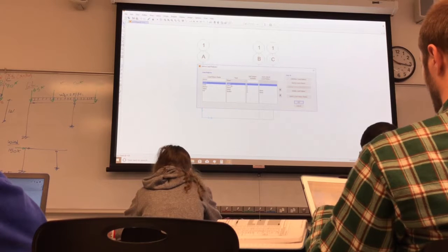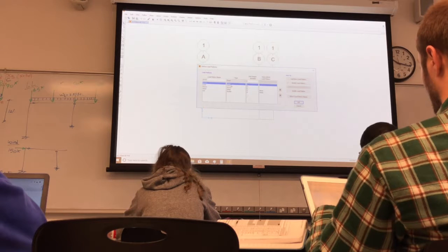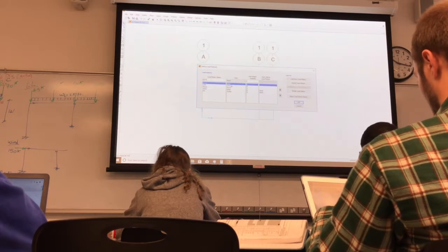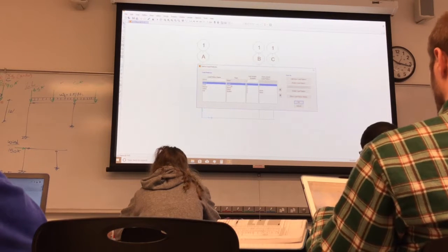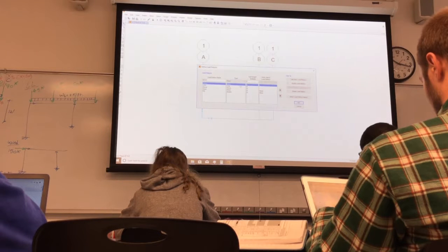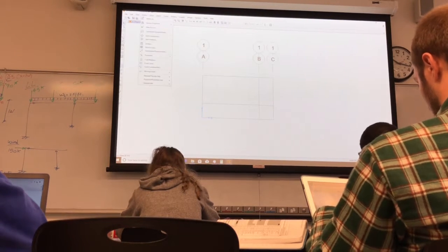And this distributed load includes the 44 pounds per foot. I already mentioned that. If it's not included, then I would have to keep it as 1. But now I don't want to account for self-weight twice. I already put it in the 3 kip per foot, and I don't want to have another self-weight, because self-weight is a dead load, right? So you click OK, and that's the load.